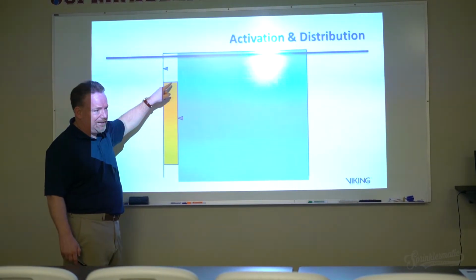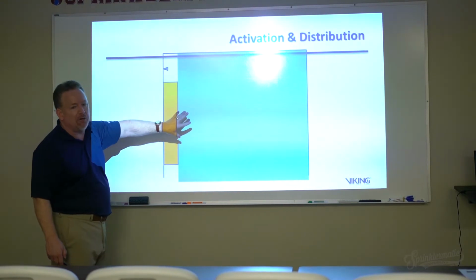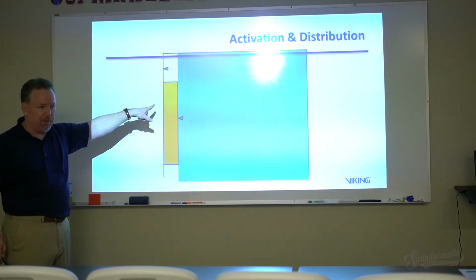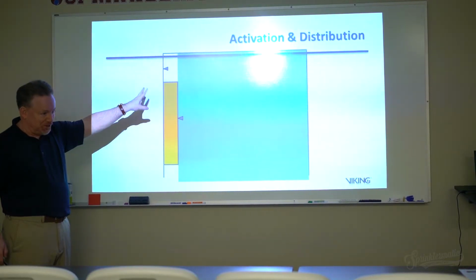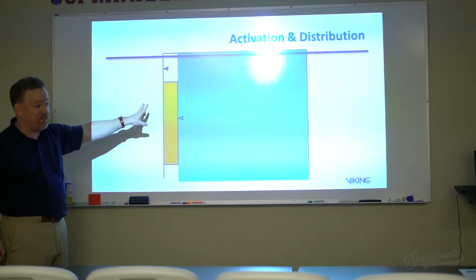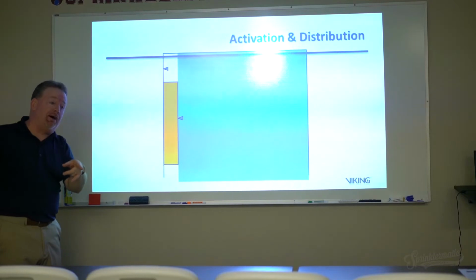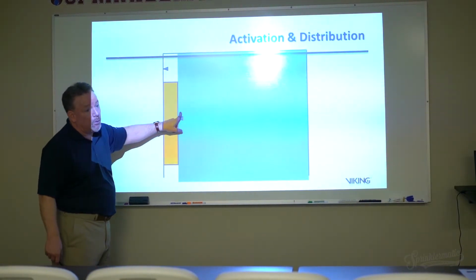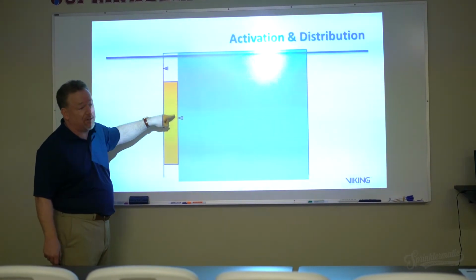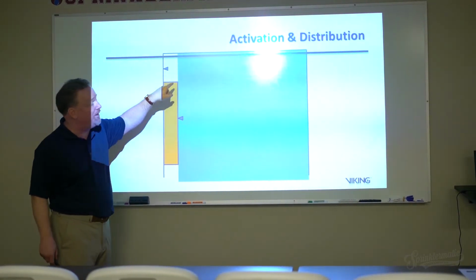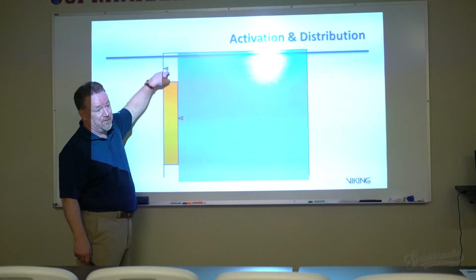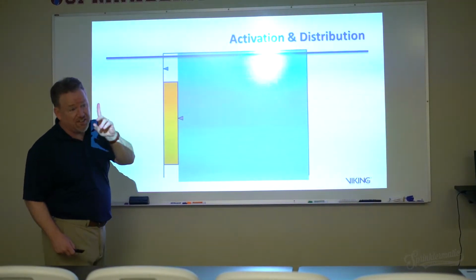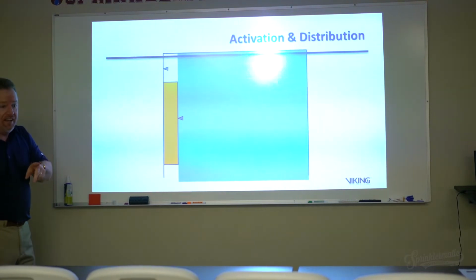Now, why did that sprinkler get required to be put there? Unprotected. Yeah, it looks like on paper that it's unprotected. What we also know about that, though, is it's not really unprotected, because of the way the water droplets interact with the air when the spray pattern comes out, there's an eddying effect too, that it'll actually get back in there.